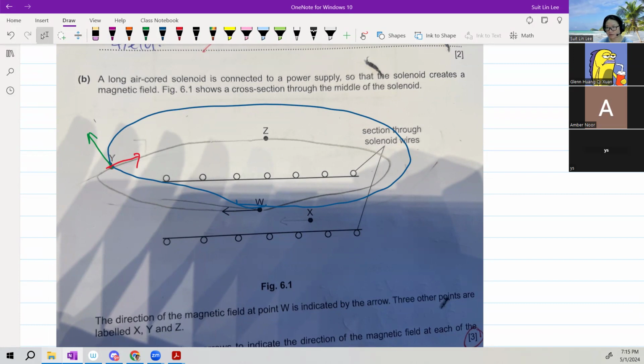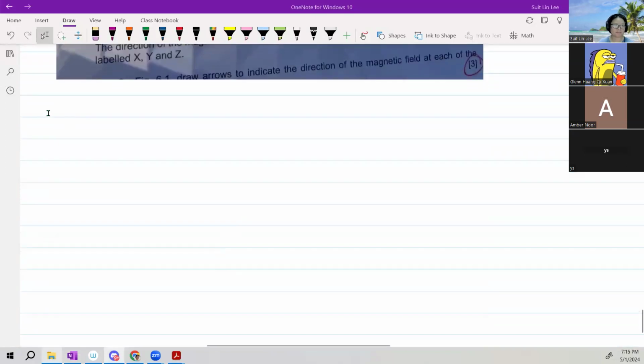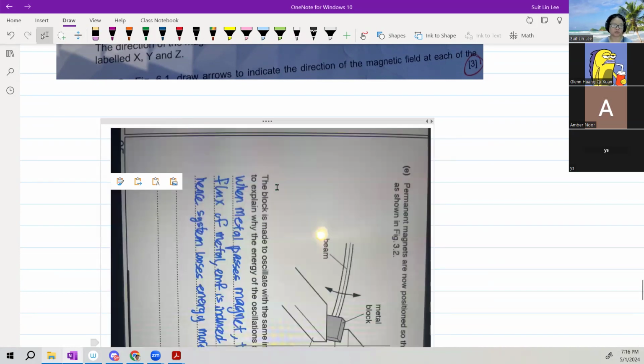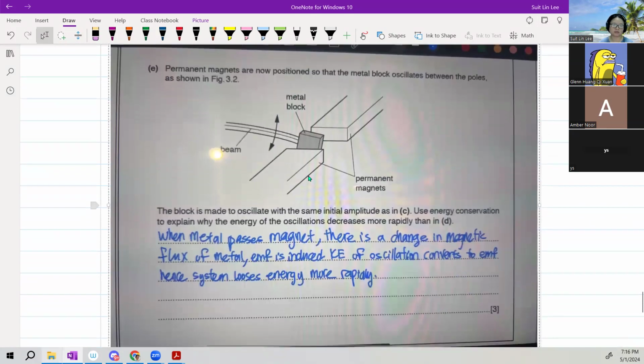Okay. How do I know whether there is eddy current? Eddy current needs space. So you don't always need to mention eddy current. You can just say current. But the short answer to how do I know there is eddy current is that it needs space to build up. So I need a 2D or a 3D conductor.